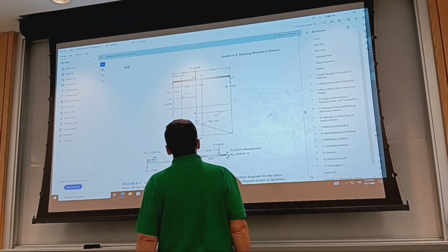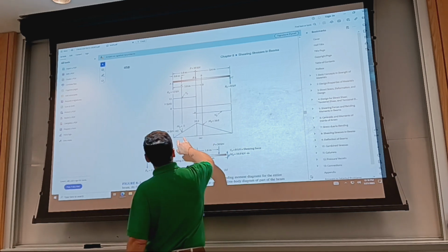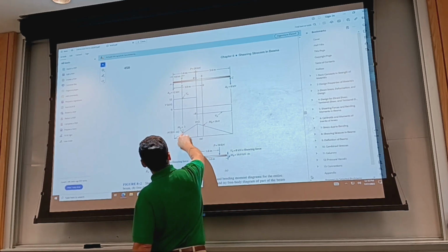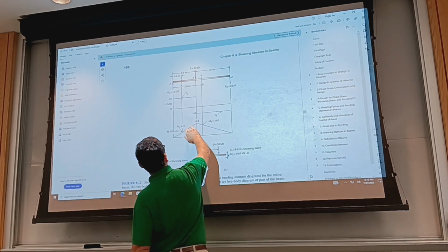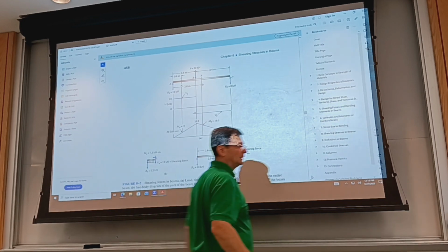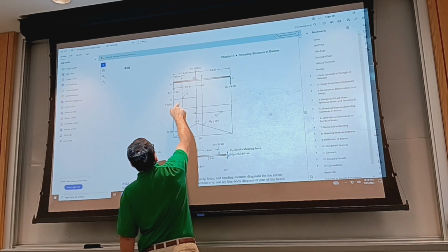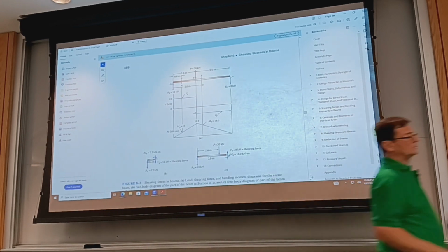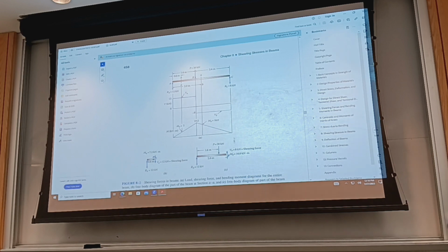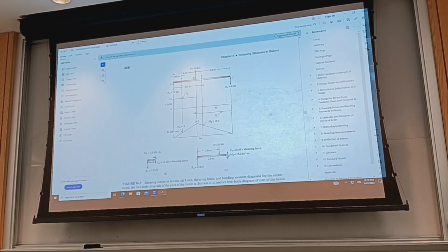So again, they develop because of the changing magnitude of the moment, and the changing magnitude is the same anywhere. And coming from the equations, you'll see we're going to use the shearing force from the shear diagram. So this first step of the analysis is required to evaluate the stress due to the shearing force.